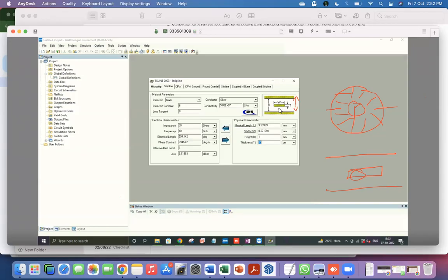They are not exactly TEM. So there are some extra aspects to the way the field lines are, and that has an effect on how the waves propagate. So the dispersion is not completely absent, but it's low enough that at the kind of frequencies one is working at, typically it's not a huge bother. It doesn't make such a big difference.